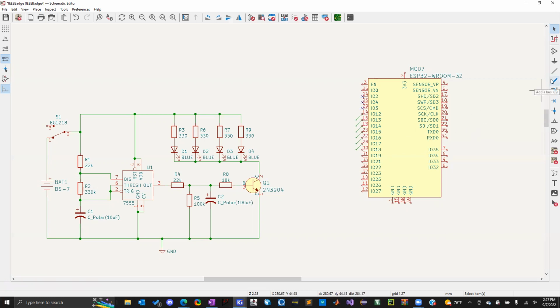And then instead of a normal wire with W, you can add a bus wire. And so all these are connecting to a common point, and then this would go to some other component and connect to something else. That's something else that KiCad offers. If you make any other mistakes, of course, you can Control Z all of it and undo everything you did.